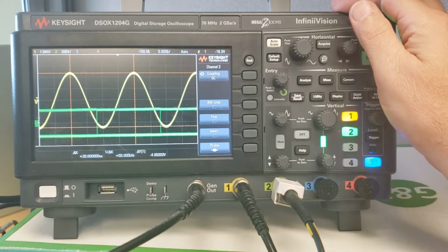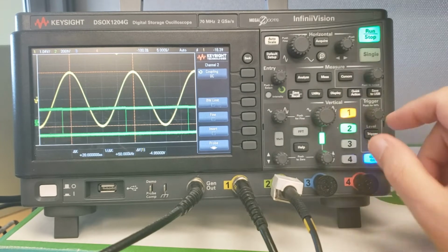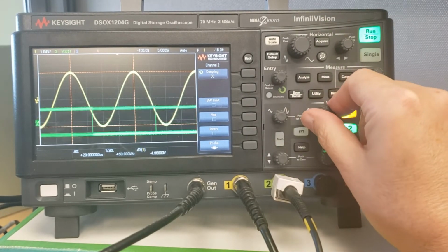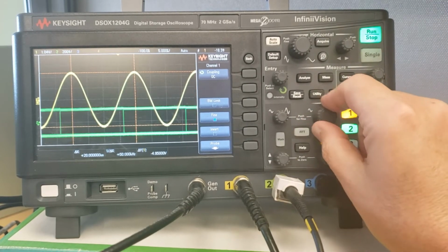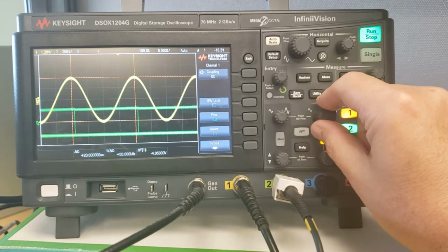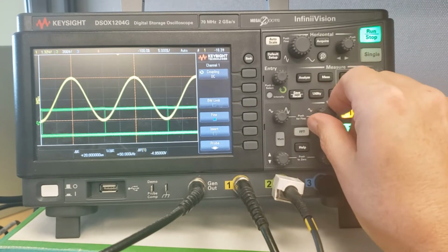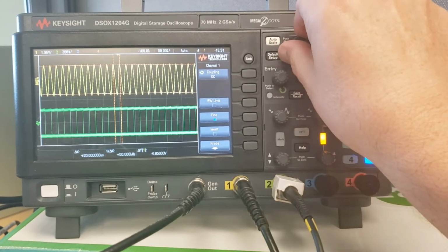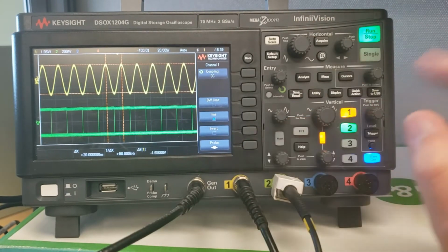Okay, here I have two different waveforms turned on. So if I want to control the vertical, I've got the green turned on, which is channel 2, and I can move that up and down. If I go to channel 1, this orange light comes on, and now I'm controlling this channel, and I can move the position. Okay, so make it a little bit smaller. Move the position, change the frequency, and you notice that the top trace is triggered.